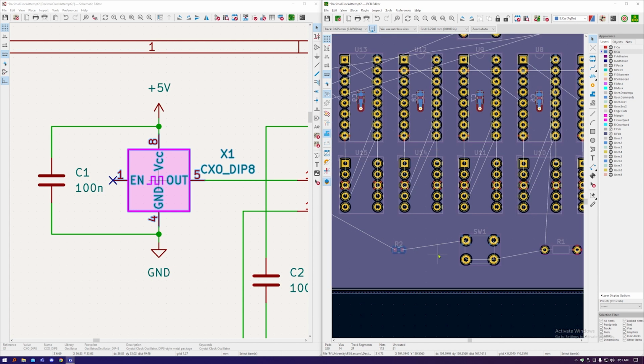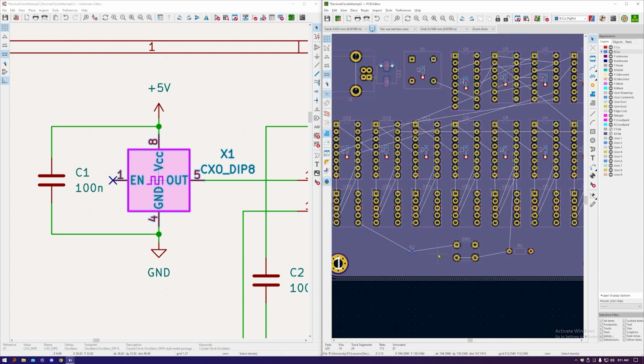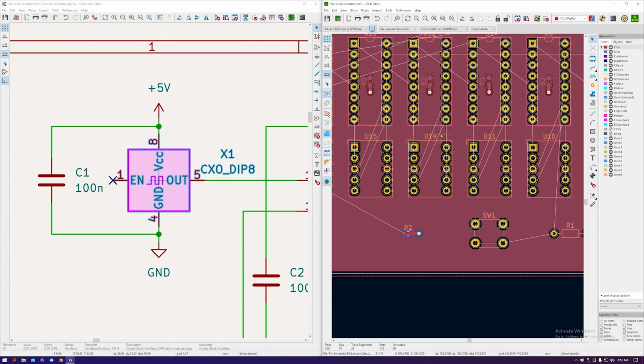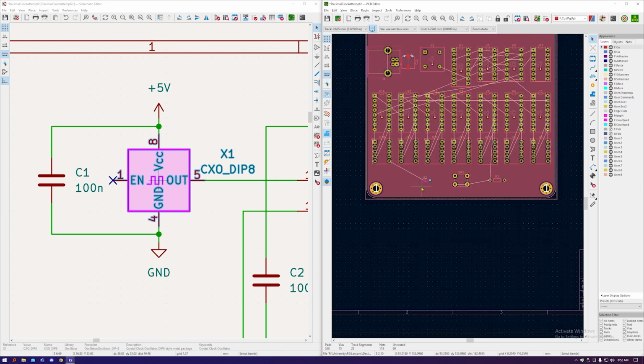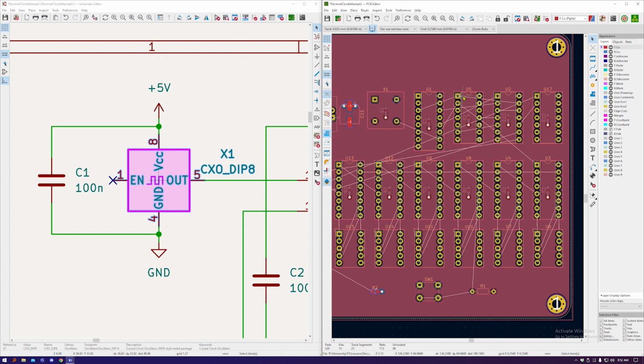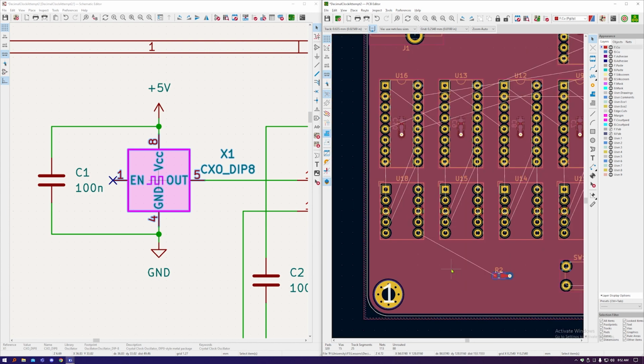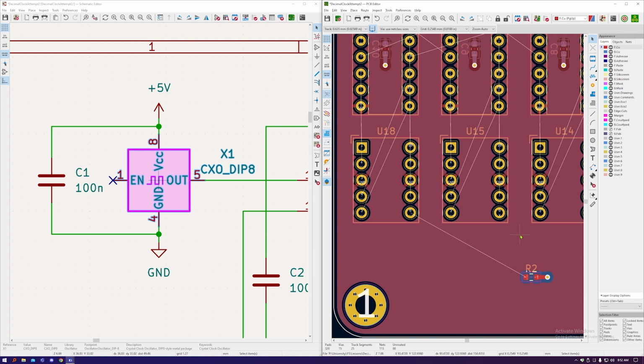The rest of the components that are connected to a rail, almost all of them are through hole. I've just spotted this resistor, so let's give that the same treatment. And that should now be everything, because all the other components are through hole, so through hole is basically a component with the built-in via, is a funny way of thinking about it. Next, let's actually do some proper traces. So I'll start with this one down here because there's a nice amount of space around it.